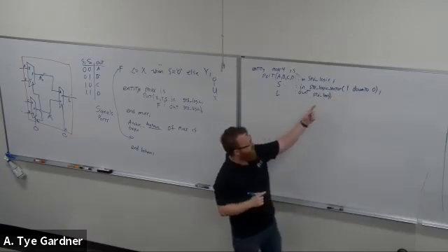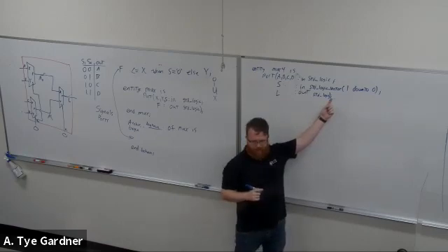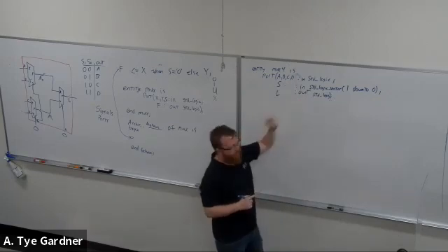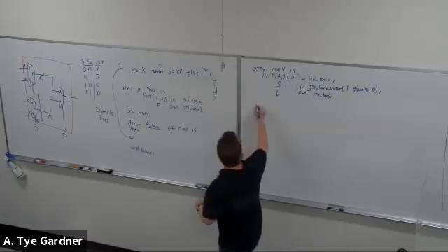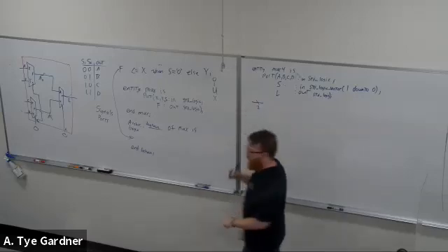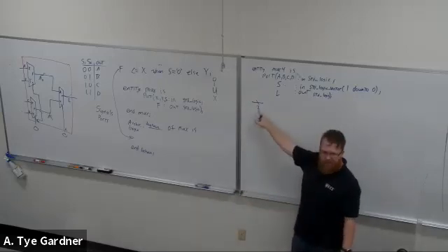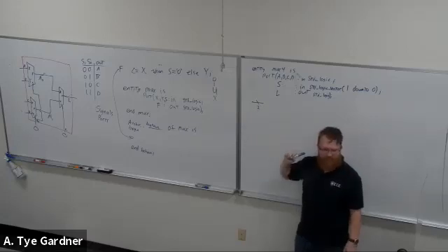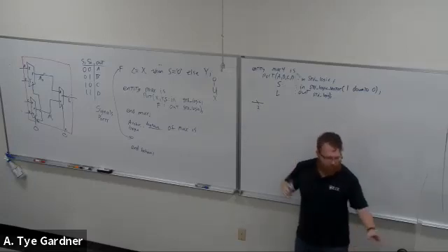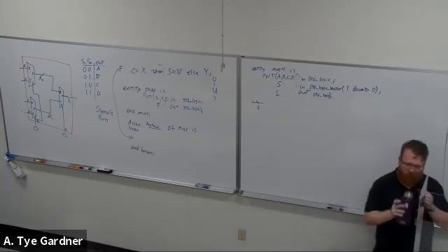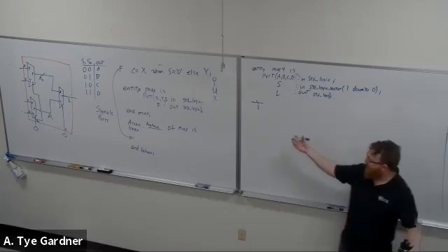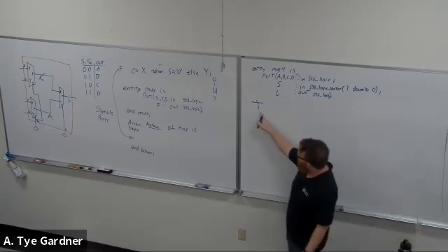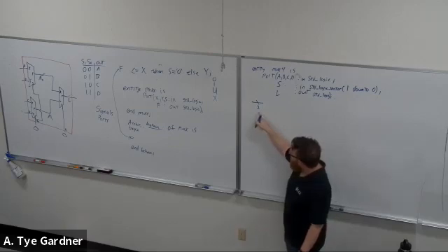The last line is a little bit different. It has a parenthesis and then the semicolon. Okay, just pay attention to that. So standard logic vector is, right, you would draw it like this. Right, it's a bus. One line that has 2 bits in it. I can then address any one of those.